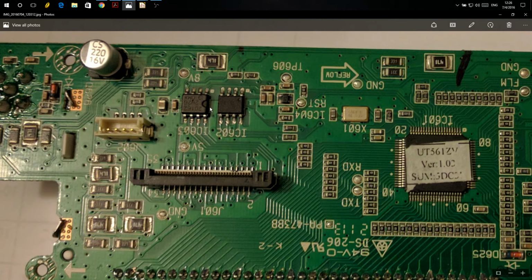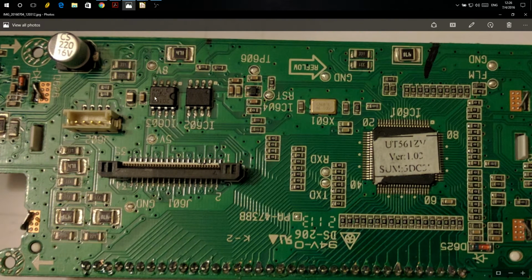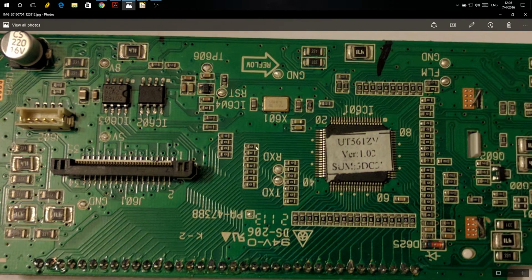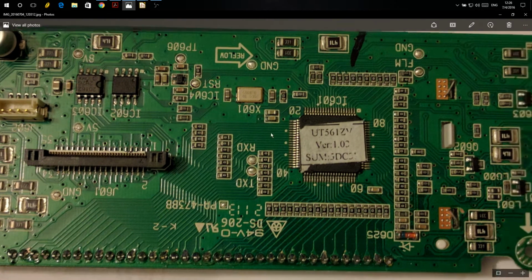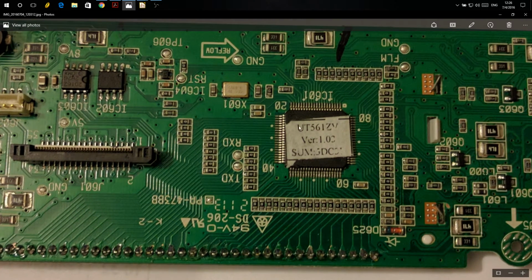So it's not like I garbled the EEPROM because they share the bus. They don't actually share the bus. This is on its own bus. So the DAC and the PLLs, the 2 PLLs in this radio, and the IO expander are all on the SPI bus. And they of course have their own dedicated chip enable lines and so on and so forth. It's SPI. So then we have the microcontroller, which is very interesting.